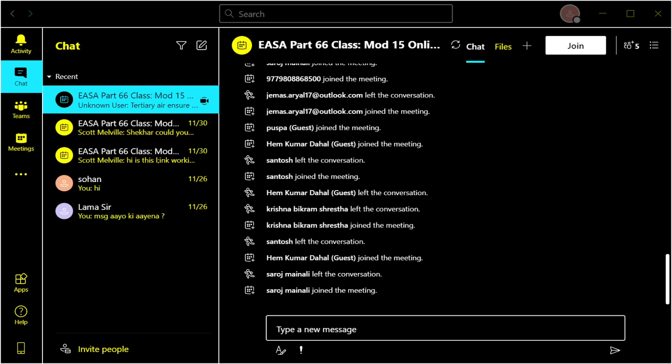All that stuff with the engine oil system, there are plenty of methods available for oil samples to be sent for analysis. I actually go down to a place in England called Kinetic, where it's a massive laboratory, and we send any samples of oil and fuel, and these laboratory technicians will sample, and they will tell you exactly what is going on with the oil, if there's any suspect contamination through fuel or whatever.